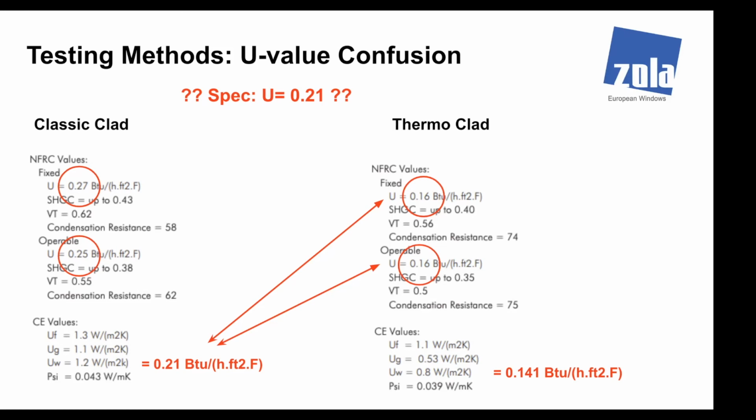But one of the things that we do in Passive House is figure out how much heat gain we actually need so we don't overheat in the summertime or even in the wintertime. So have you been able to use higher solar heat gain coefficients in projects for architects that haven't actually run the ASHRAE 90.1 calculations?